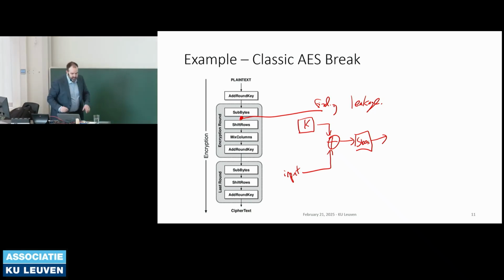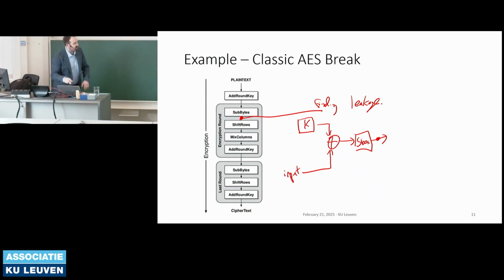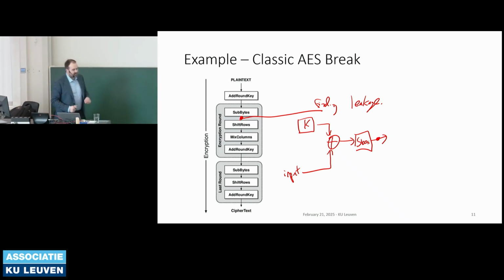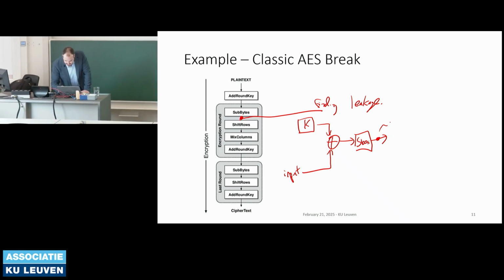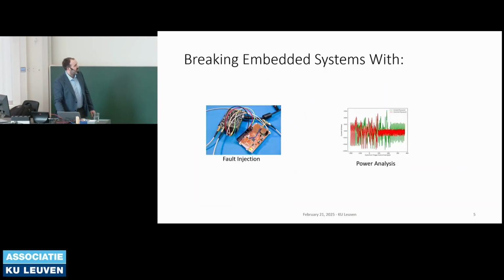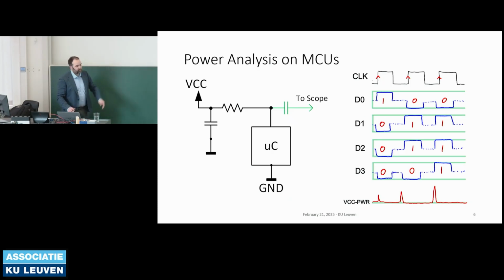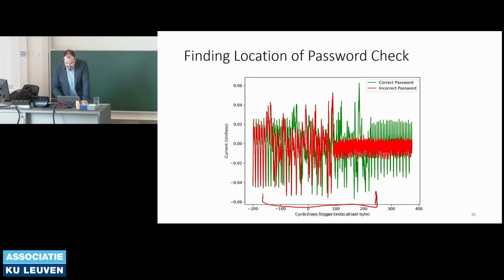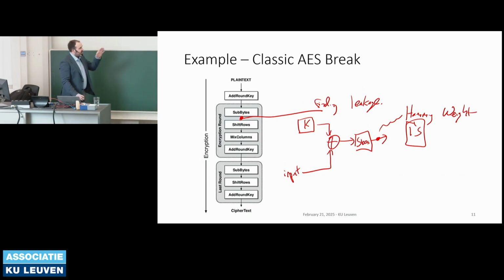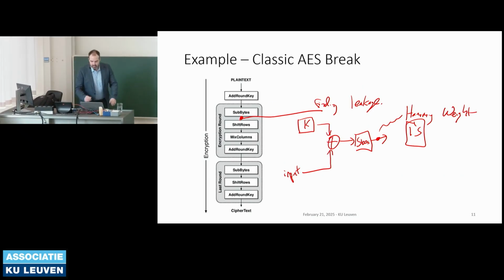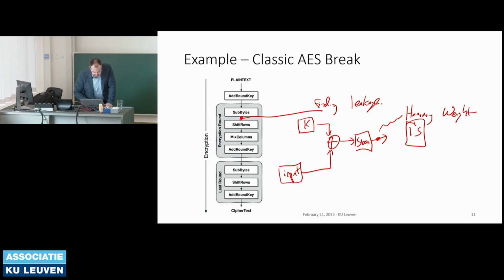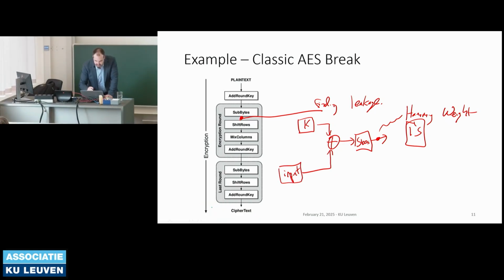So at that point, if I put a dot here, there's a dot on the little diagram, a dot on the input to AES. And so we're going to figure out the Hamming weight here, which is basically just the number of ones, which is what I mentioned through side channel power analysis, we're able to determine. Because we know the number of ones at this point in time, we know our input data. What we don't know is this secret key. I'll draw in green here, right? So this is an unknown.